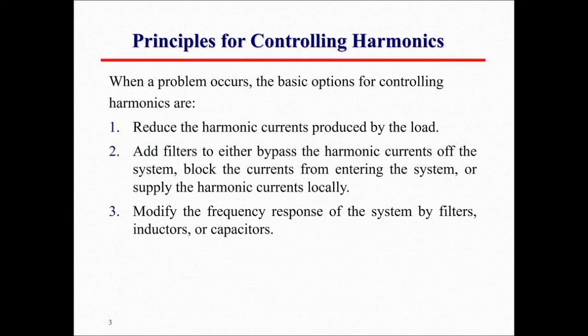When a problem occurs, the basic options for controlling harmonics are: number 1, to reduce the harmonic current produced by the load, and we're going to talk about several methods that can be utilized to do that. Number 2, adding filters, and we have already discussed this one. Number 3, modify the frequency response by using inductors, capacitors, or even filters. Let us first of all look at the first point, how to reduce the harmonic current